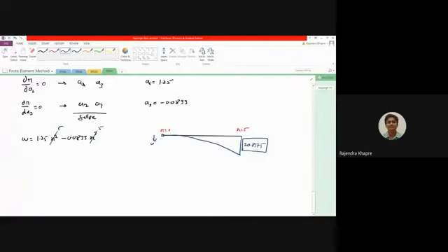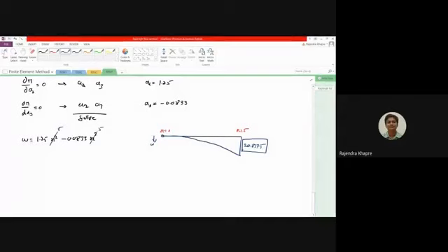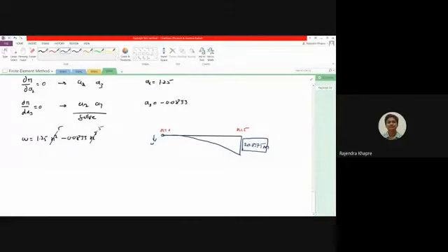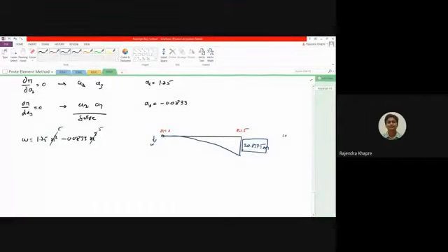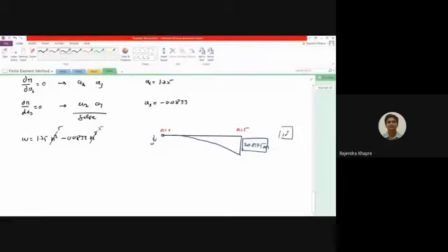I think there is some mistake with the units conversion, because ideally the value should be in meters, and this much meter deformation should not come. I think there is some issue with the power term, we missed 10 to the power 3 somewhere. Sir, due to the value of E. Due to the value of E. Because E is given in kilonewton per meter square, that 2 into 10 raised to power 5, it should be in Newton per mm square. Quite possible. Anyway, all I'm trying to say is that there is some issue with the power term, otherwise the numerical value is perfect.